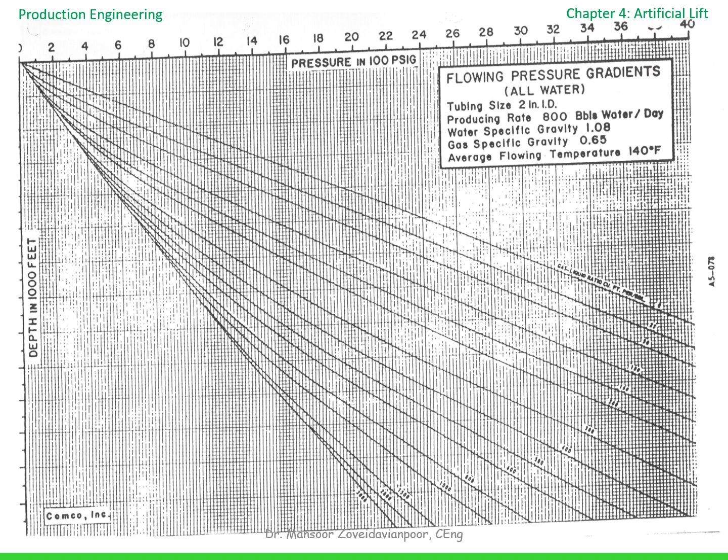This is the same pressure distribution chart used in the previous calculations. Once you know the operating conditions, you use the chart to estimate tubing pressures and determine the corresponding GLR. For the exam, focus less on memorizing the chart and more on understanding how to use it.